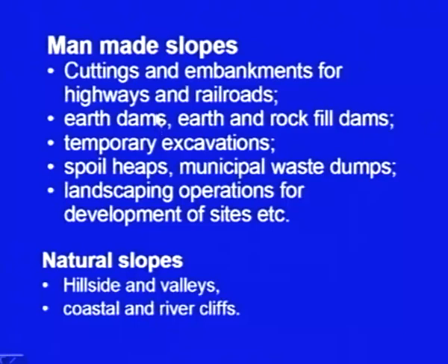Stability of slopes from the soil engineering point of view is important in the case of earth dams, because an earth dam will be storing water on its upstream side, water will be seeping through the body of the dam, and because of the seepage there are certain forces which act on the dam body, and then stability is a major concern. So, for earth dams as well as earth and rock fill dams, you have to consider the stability of slopes. You have to design them in such a manner that they are safe.